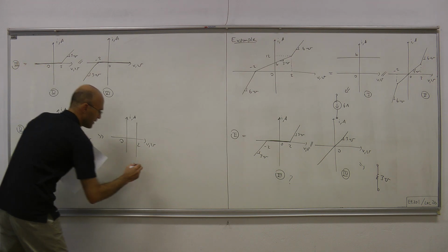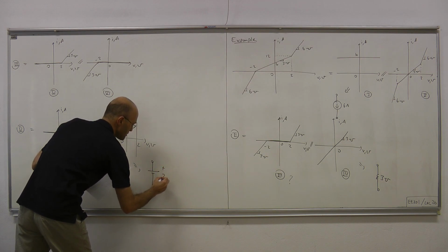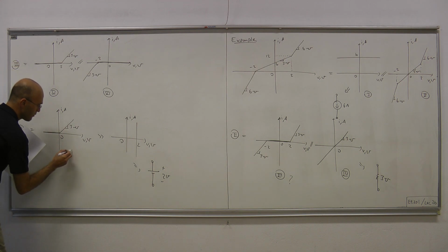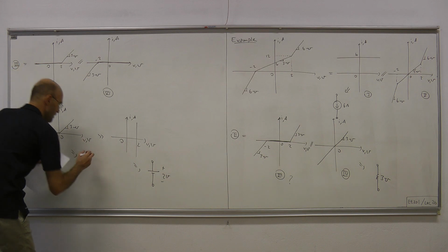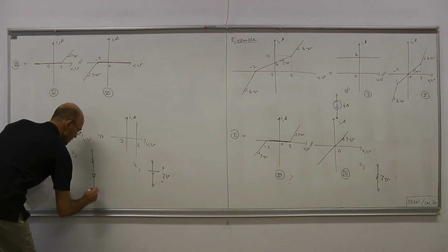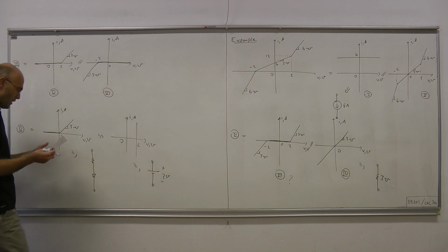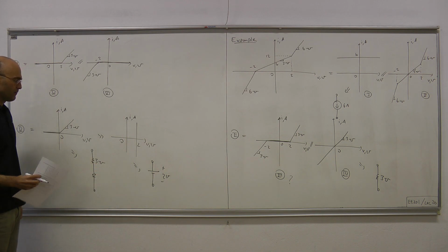This we immediately recognize as a battery, plus minus 2 volts. And this 2 we also, from our previous lecture, know at this point what it is. It's an LTI resistor connected in series with a diode. 3 mhos and an ideal diode.